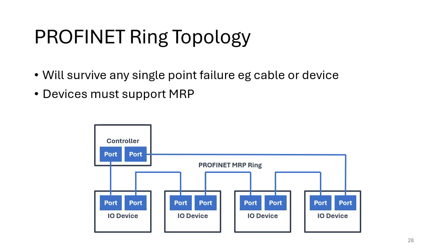Maybe there's some more catastrophic failure, which is also very common. We see issues where maybe a device catches fire, or there's a fire in a panel, or a flood. So devices in those cases can be catastrophic, and that's very difficult to calculate. But you can do failure mode effect analysis to try and understand effectively what might go on, and use that to guide how the system will work. But normally, if you've got some sort of disaster like that, the fact your machine is stopped is often the least of your worries.